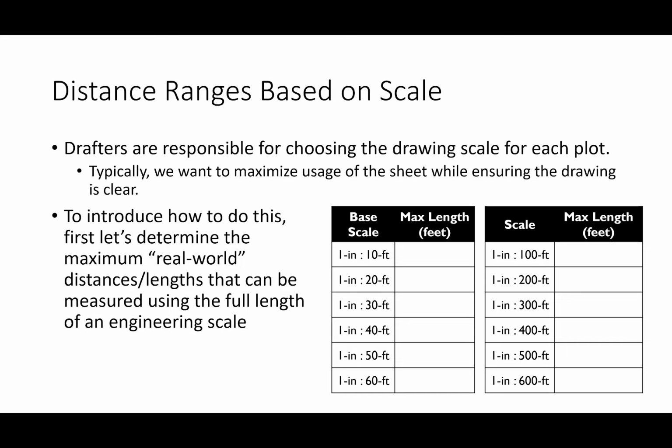Okay, and typically what we want to do is maximize the usage of the page. We want to make sure that the page is being used as much as possible. In other words, if I'm going to have a drawing that's on a 24 inch by 36 inch sheet of paper, I don't want a detail that's that big. If I'm going to print, I want the drawing or the schematic to fill up the sheet as much as possible.